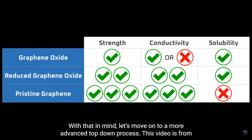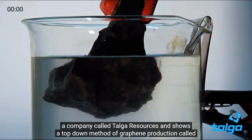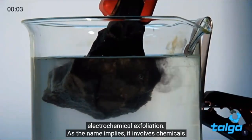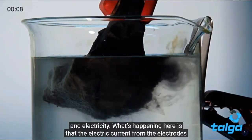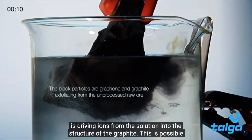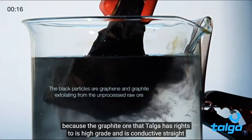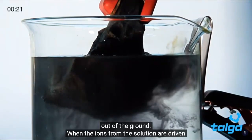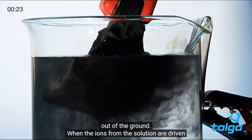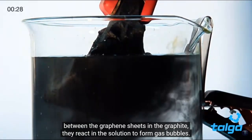This video is from a company called Tolga Resources and shows a top-down method of graphene production called electrochemical exfoliation. As the name implies, it involves chemicals and electricity. What's happening here is that the electric current from the electrodes is driving ions from the solution into the structure of the graphite. This is possible because the graphite ore that Tolga has access to is conductive straight out of the ground. When the ions from the solution are driven between the graphene sheets and the graphite, they react in the solution to form gas bubbles. The gas bubbles split the graphite layer by layer, causing the graphene to exfoliate.